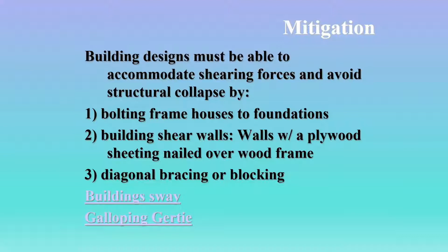You tack that on, and now all of a sudden it's a solid structure. That's the idea of putting in the plywood. Putting in the plywood before you put in the finishing, like the drywall, adds an additional level of shear strength to your house.